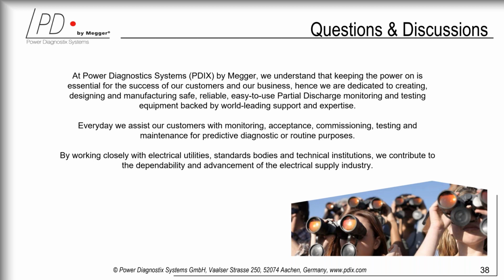No, there's no need to be on site to view the information. As Mia did show on a few slides, we have this remote communication module to the instrument via a mobile network. We have remote control over the local network of the substation. So we can check all these values from the control room and the substation or in the office of the utility. We do these kind of remote measurements here from Aachen also for some of our customers, and we take measurements, do consulting remotely.